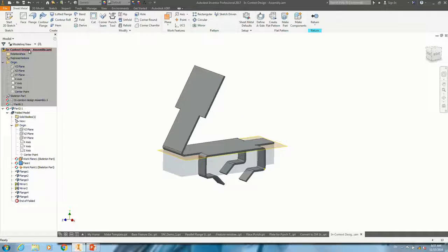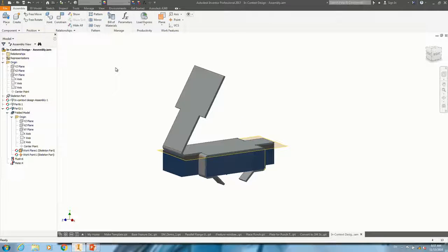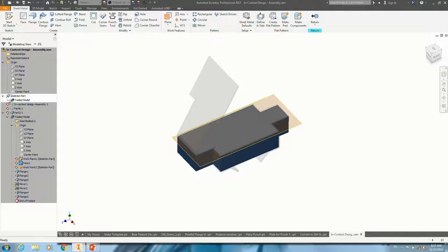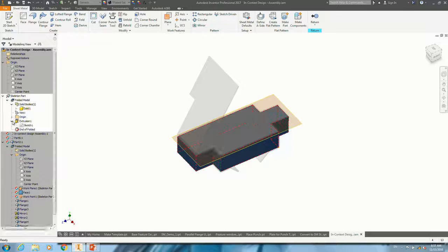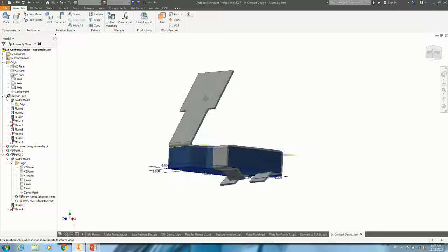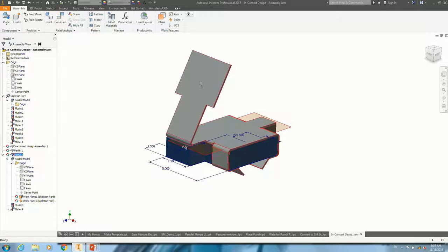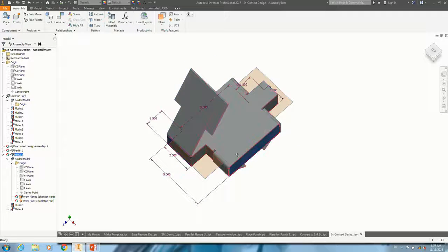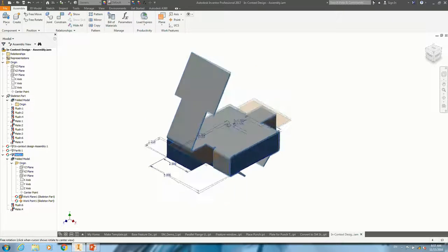Okay. And now we just do these steps. It's enough. So we go to the skeleton part and show this sketch, and change the width to be 5 inch. Do update. Okay, I need to go back to this. So you see this part has been updated associatively with this skeleton model, right?